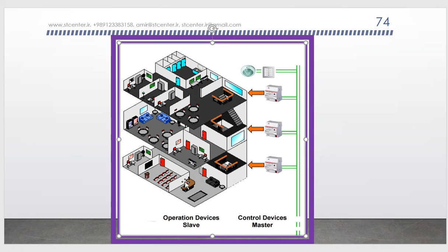Dali devices, like the driver, are placed in the field level of BMS. We can have the controller in the control level of BMS or use the monitoring level as a BMS or BACnet. So the upper level is the Dali gateway to KNX or BACnet, and the lower level, I mean the field level, is the Dali driver. Because of that, KNX is a good solution for that.